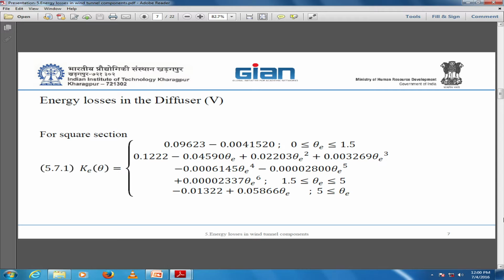They are going for the simple sheet metal because the difference of loss between sheet metal and profile is not so significant, and the investment in profiles is bigger. So at least in my last 2 wind tunnels, I was working on simple bent sheet metals.